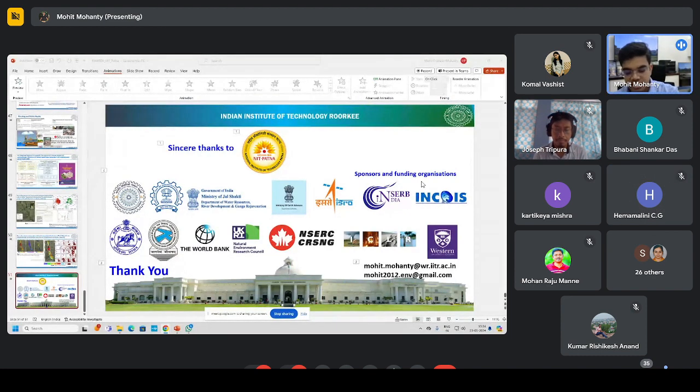For the coastal case study, the first point will be the coastal ocean. Basically, we have two different things. One is a very dynamic component, which is the tidal part. We term this as storm tide. Tide is more or less stable for almost 17 to 18 years. But during local depressions or cyclone activity, when wind is associated, the tide height also increases. That is what happened in the Mumbai flood, where the tide height was around 5.3 meters. So we term this as storm tide.